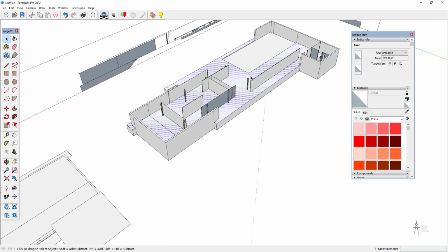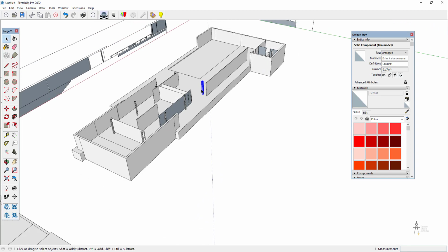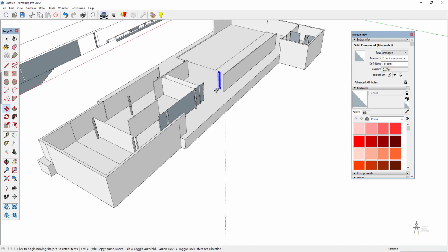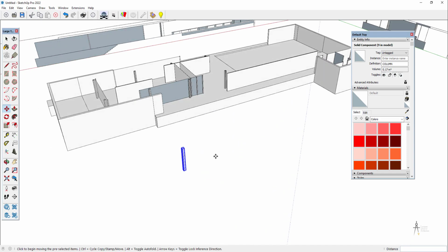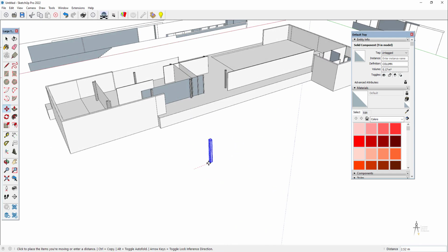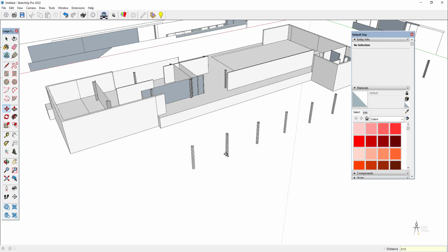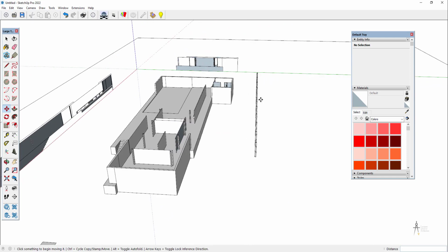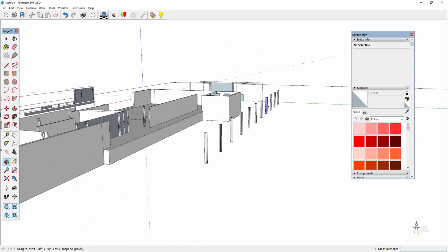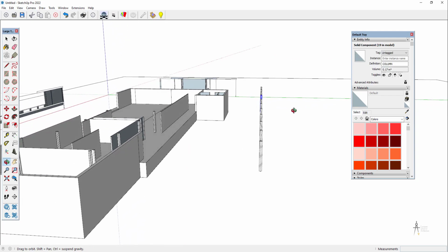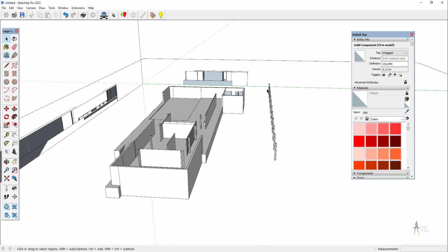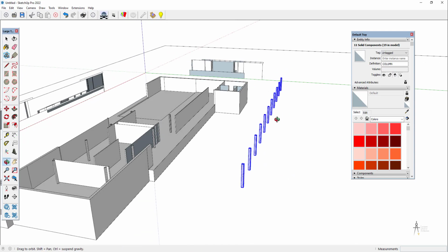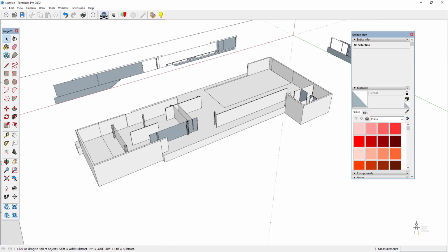And I'm going to use this moment to teach you a quick trick with the command copy. Okay, I'm going to copy this pillar here on the floor, and let's imagine I know that I want the next pillar to be at a distance of 5 meters, so I type 5. But if I type X and then 10, what I'm going to create is a line of 10 elements, okay, copied at the same distance. So for architecture, you can imagine this is also very, very useful to copy elements, to copy pillars, walls, all sorts of things.